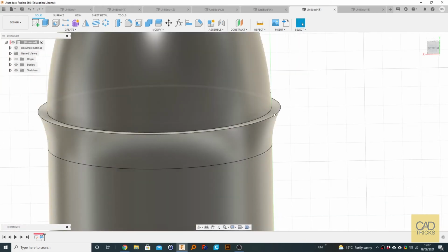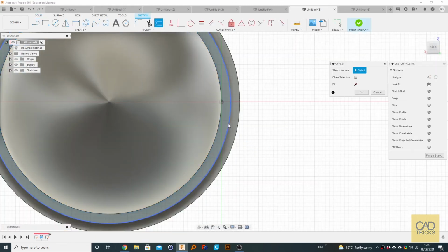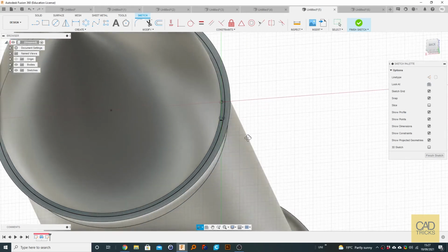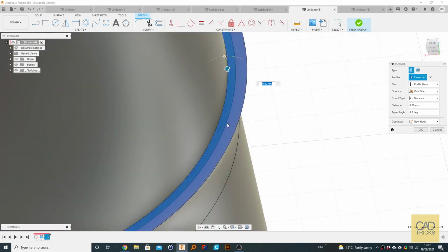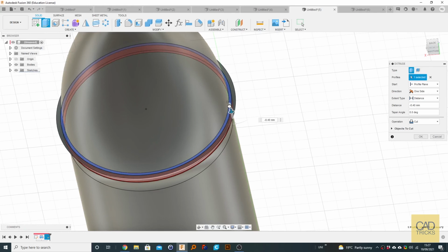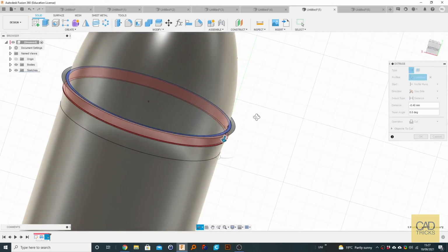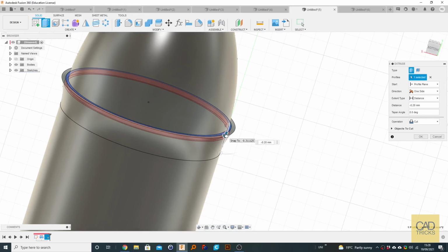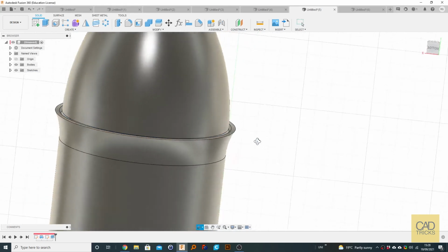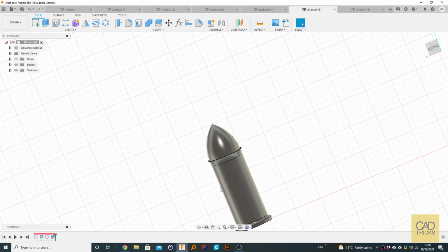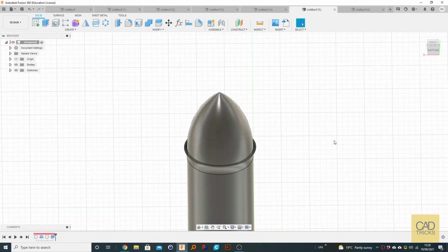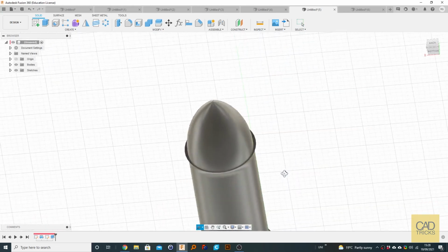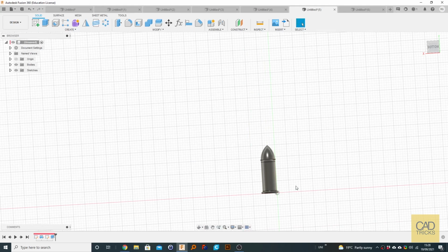If you want to do it, I would just do an offset here, and offset it by 0.1. Obviously this is not to scale, so the dimensions are extremely small, but in reality they'll probably be a bit bigger than that. You don't really need to do much because it's only a fake. We're only faking it, to be honest. It's not a real separate component. So if you do Control-4, it looks like it's a separate piece now. Control-6 brings the lines back.